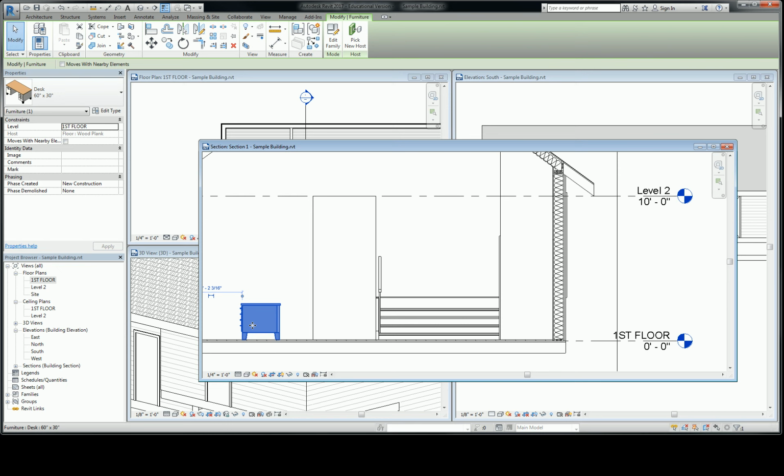So it wouldn't be able to interact with the system walls. Right. It wouldn't wrap. It wouldn't create clean corners and stuff like that. Like the cabinet, you can't put it into the wall. It wouldn't react to the cabinet. I mean, there are cabinet families, and they are wall-based cabinet families, but they wouldn't react with the wall that you self-created as a regular family. That's correct. Can you fix that, or is that? Not really. I mean, you could create nested families and stuff like that, but no, not really. I mean, there's just no reason to.